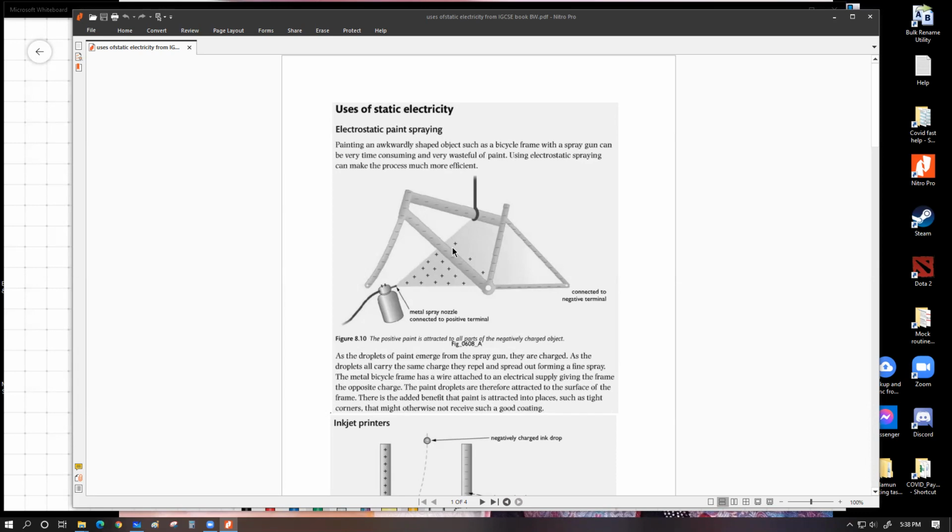The second thing that we can do is spray painting. In the process of spray painting, we have some liquid paint within a pressurized canister. We use compressed air connected to the container that applies significant pressure on the liquid, and then we can press the nozzle, and the paint is going to come out in small droplet forms that can essentially get stuck on a surface.